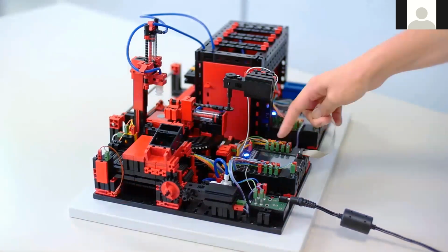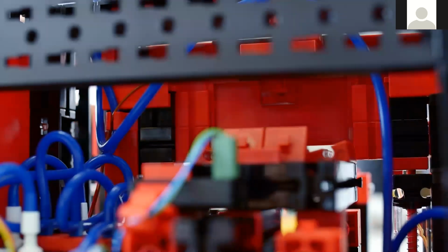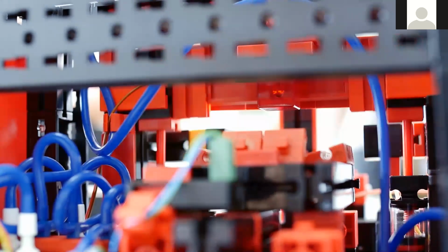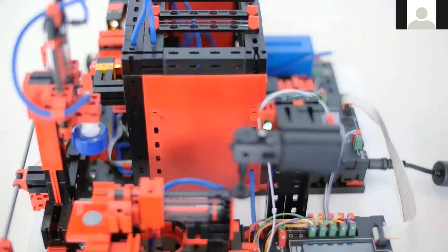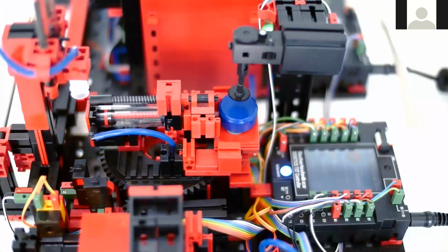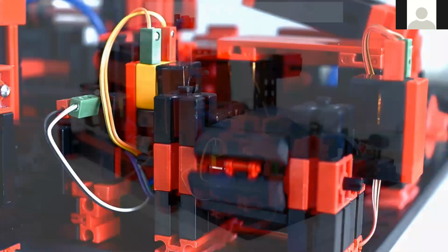The dimensions for this model are approximately 20 by 14 by 12 inches, and it has a weight of about 11 pounds. Again, the standard version of the model is a 24-volt version for use with the PLC of your choice, with once again a relay board for motor polarity reversal and both a multi-pin connector, 34 pins with a grid of 2.54 millimeters, as well as additional PCB terminals with push-in connections for all inputs and outputs. The limited edition 9-volt version in this case is connected to two robotics TXT controllers, so here 2 120-volt power adapters will be required for all operation.